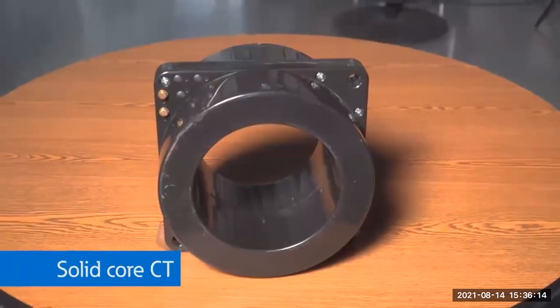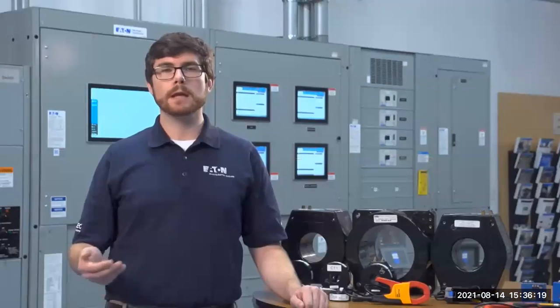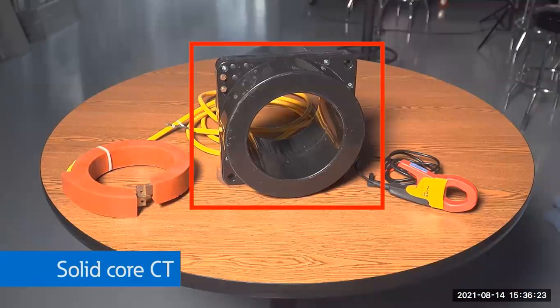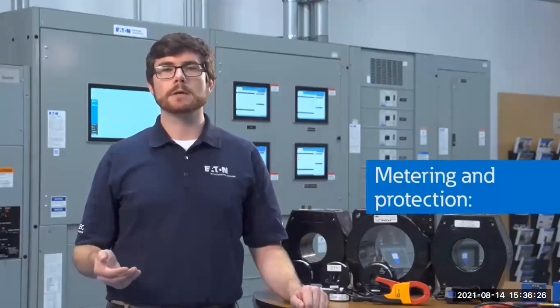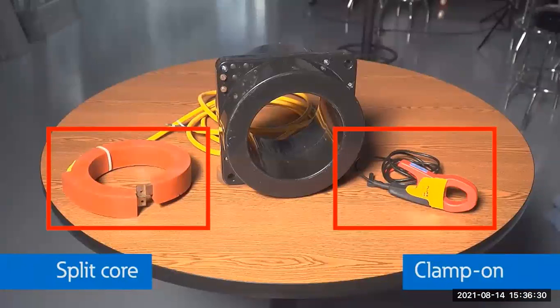CTs can be solid core, split core, or clamp-on styles for both low voltage and medium voltage applications. Solid core CTs are generally more permanent and are most commonly found for metering and protection in switchboards, panel boards, and switchgear. Split core and clamp-on CTs are generally used in more temporary applications such as power quality instrumentation. For permanent applications of protection and metering, CTs can be found anywhere from generators to transformers to connected loads, or anywhere we want to monitor current flowing in the system.